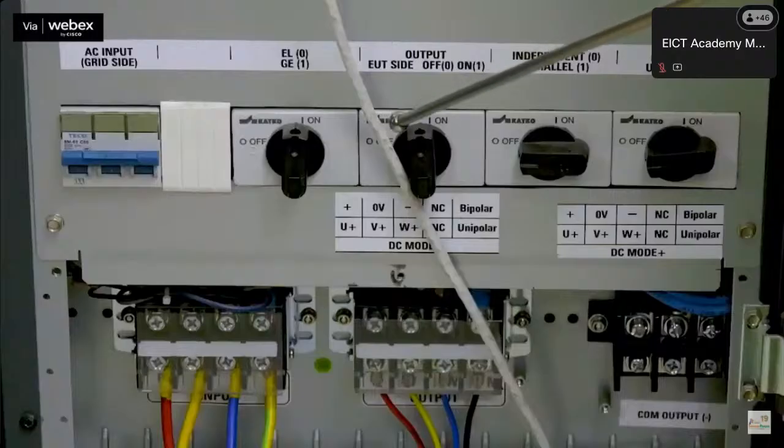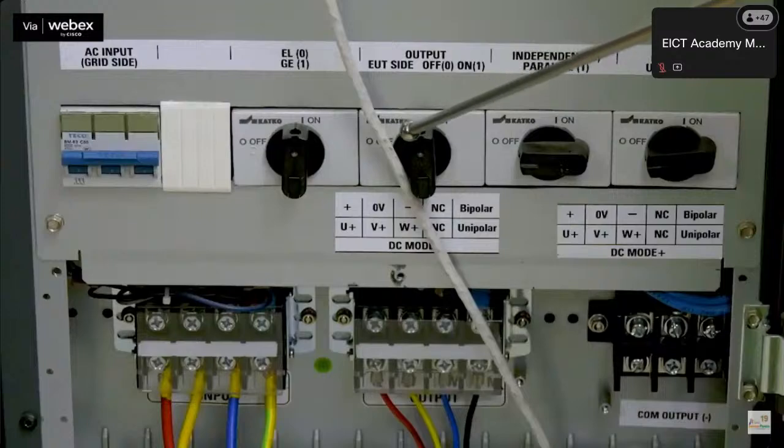Initially, the device working mode switch is at 1. This represents that the operation mode of the device is DC. By configuring the 4 switches, the functioning of the device can be modified. After configuring it in DC mode, the switch combination decides various functions such as DC source emulator, DC programmable load, battery emulator, and PV emulator. In this video demonstration, we are mainly interested in showing how to configure it as an AC grid emulator.